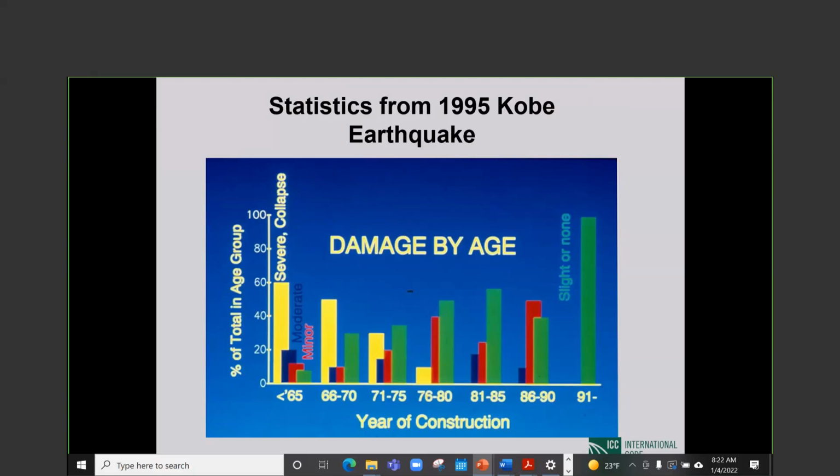And then in 1991, following another devastating earthquake, they made a major code change where they introduced a two-part design procedure. You design for no collapse under a severe earthquake, but you also design essentially for serviceability under very frequent earthquakes. And since then, code complying structures have done really wonderfully in Japan. So this shows you that building codes, properly formulated and properly enforced, can directly save lives.